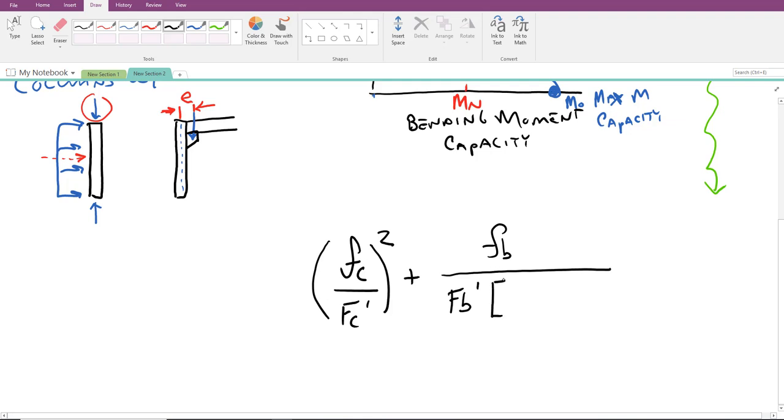And then there's one more embedded parameter here, 1 minus the compressive stress over the Euler critical stress. And what this particular term does is account for Euler's buckling right there. So in a nutshell, we've got the ratio of actual compressive stress to the allowable. We've got the ratio of actual bending stress to the allowable.